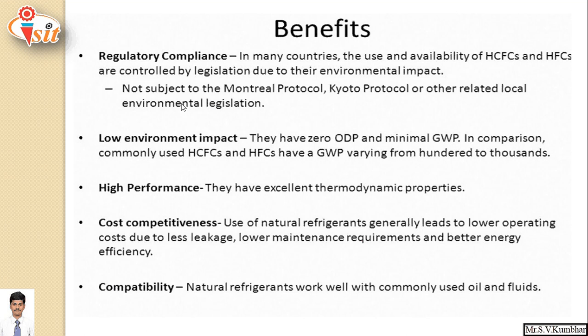Benefits. Regulatory compliance. In many countries, the use and availability of HCFCs and HFCs are controlled by legislation due to their environmental impact. Under the Montreal Protocol or Kyoto Protocol or other related local environmental legislation, a few refrigerants are banned. Low environmental impact. They have zero ozone depletion potential and minimal GWP. In comparison, commonly used HCFC, hydrochlorofluorocarbon, and HFC, hydrofluorocarbon, have a GWP varying from 100 to 1000.